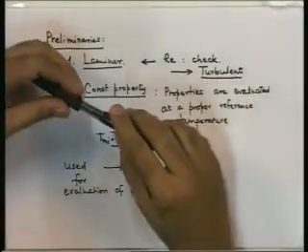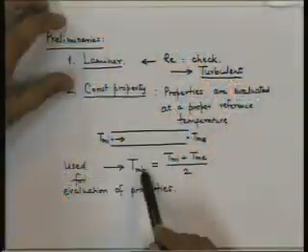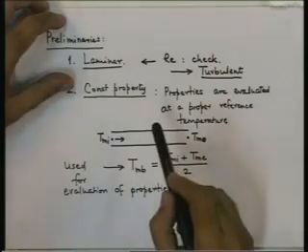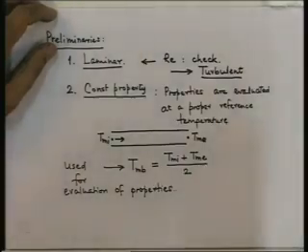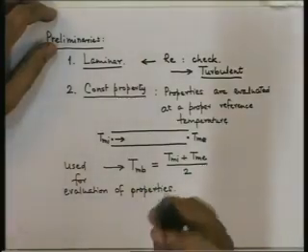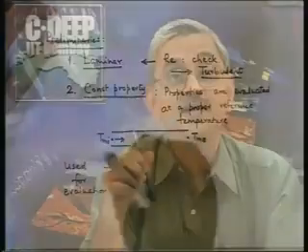However, the authors of the correlation may specify a different temperature for property evaluation. It may be a modification of this, or they may take the mean bulk temperature and wall temperature and take the average of that. So whenever you look at a correlation in a book or a handbook, read around that, find out the conditions under which it is applicable and the mean temperature at which properties are to be evaluated.